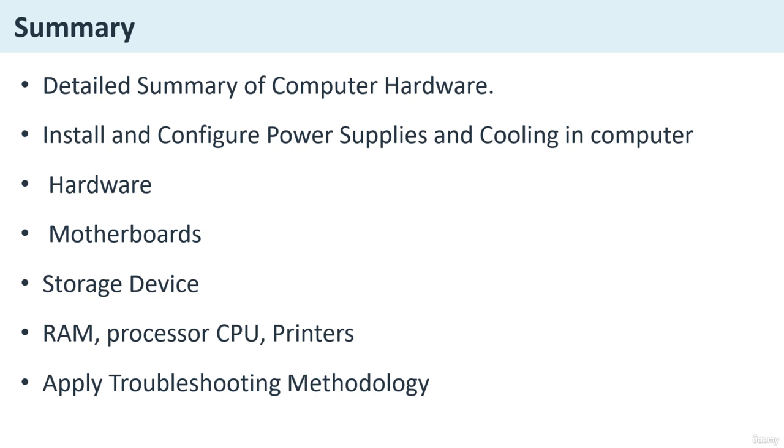Number two is CPU cooler. It is a fan attached to the processor to keep it cool. Number three, case fans. They help circulate air inside the case. The second type is liquid cooling. It uses liquid, usually a coolant, to absorb heat and transfer it away from the components. One is AIO, all-in-one coolers, that is a pre-built liquid cooling system for the CPUs. And the second one is custom loop cooling, that is an advanced setup with separate pumps, reservoirs, and radiators.